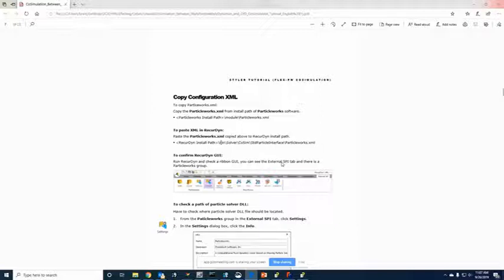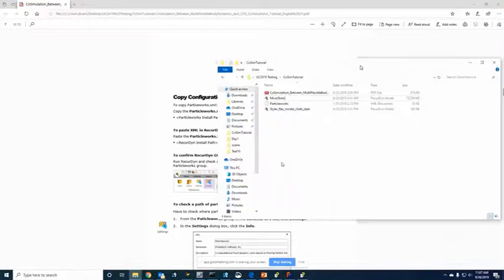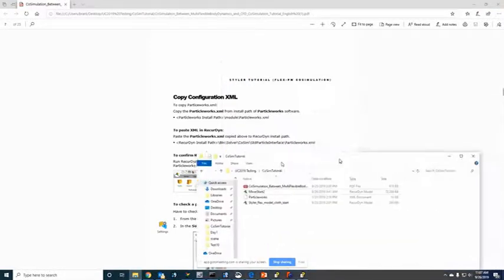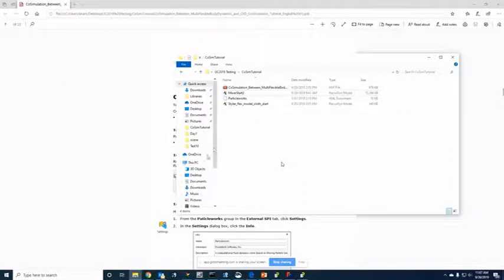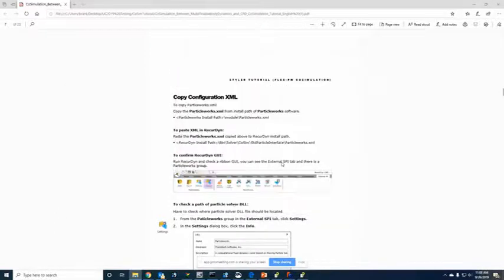From there, it's bin, solver, cosim, std particle interface, and that's where you would paste it. So it's a bit of a path to get there, but it's not too difficult. And I'll briefly show where that is.